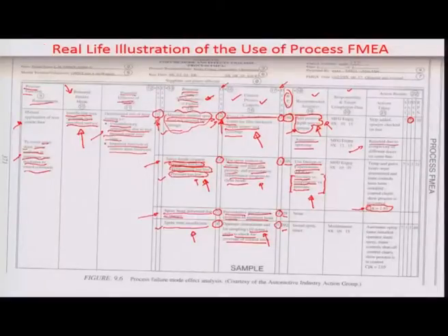Okay, and so whether the temperature and pressure limits are obeyed or not gives you an idea of what is going to be the fraction defective coming out of the particular line. So it's recommended that a P chart be plotted in this case in order to monitor the deviation, if any, from the optimized parameters which have been found out using the DOE.